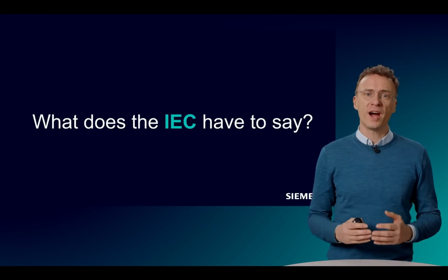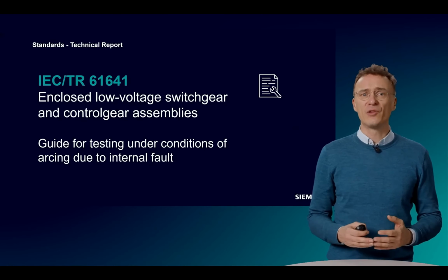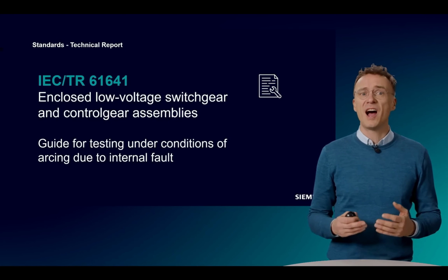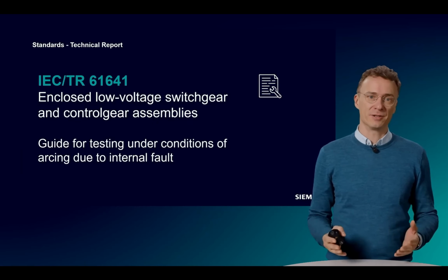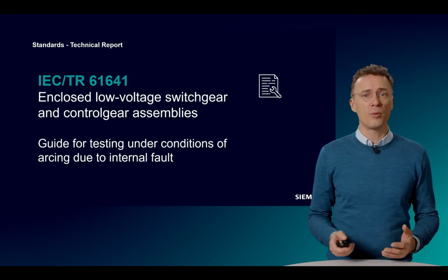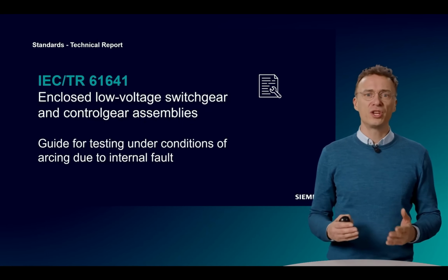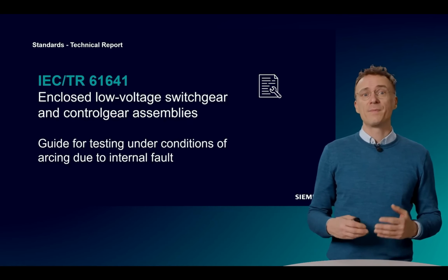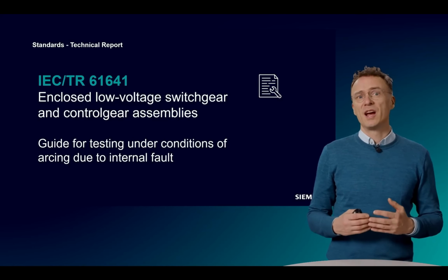A technical report from the IEC standard series is helping us. IEC Technical Report 61641 describes the requirements for testing low-voltage switchboards under the condition of arcing. Technical report means that it is not a standard. It's an informative document that reflects the state of the standardization and can be incorporated into a standardization work later. No measures are defined how to achieve arc fault protection. This is left to the manufacturer. However, it defines how the test is to be carried out and how the test result is to be evaluated.